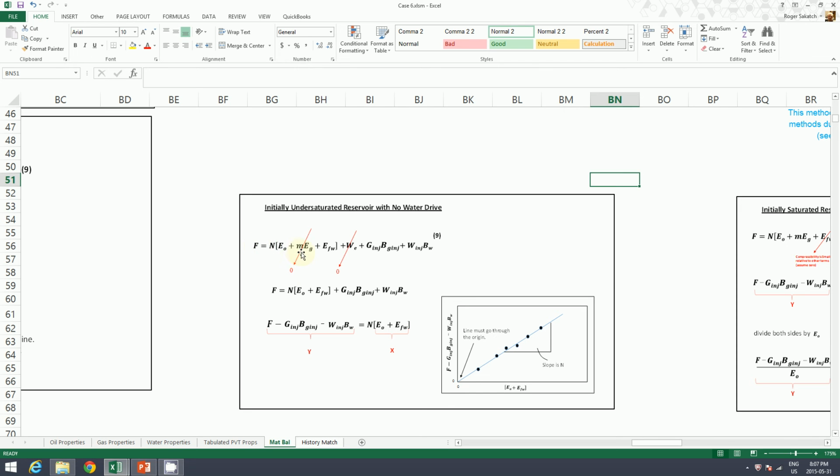So in that case, we're going to take that material balance equation we were just looking at, and we're going to realize, first of all, M is 0. There's no gas cap, so we're going to strike that out. And we're also able to strike out the cumulative water influx. How can there be water influx if there's no aquifer? So both those come to 0. And so therefore the equation can be rewritten in an even more simplified form, right where my cursor is here.